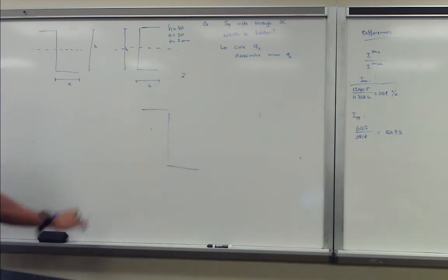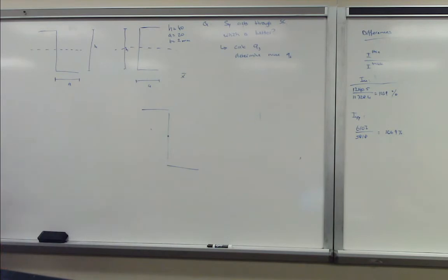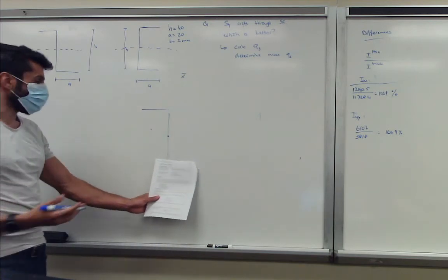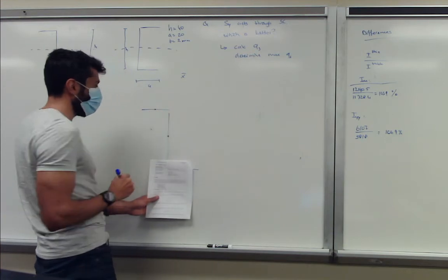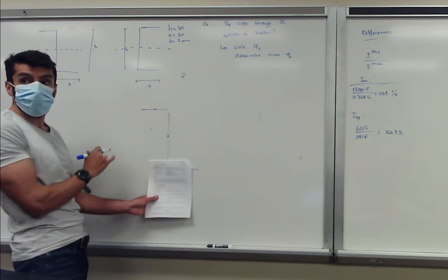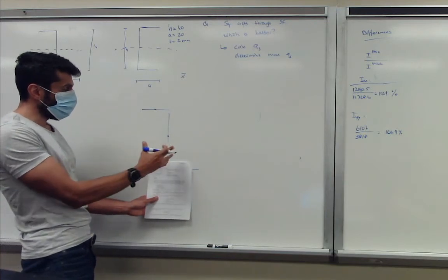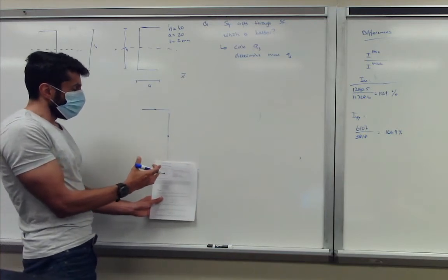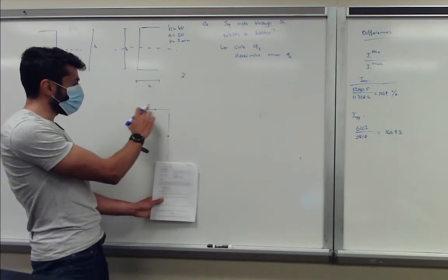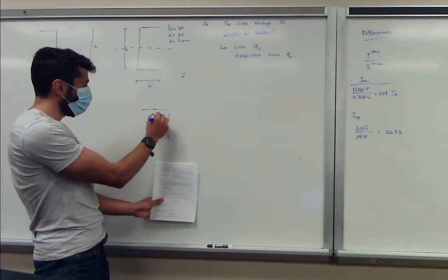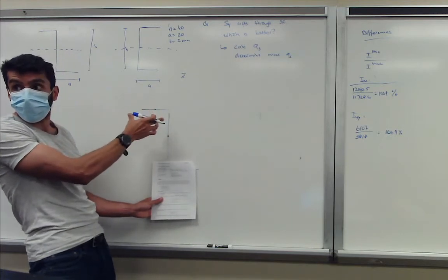So the centroid of the center one lies in the middle. That one's straightforward, right? So now imagine what this part does. This local centroid also is in the middle of its own local axis. So if this was your cross section, your general centroid will, due to this top flange, be shifted up and a bit to the left, because that's where basically the mass area centroid is located, right?